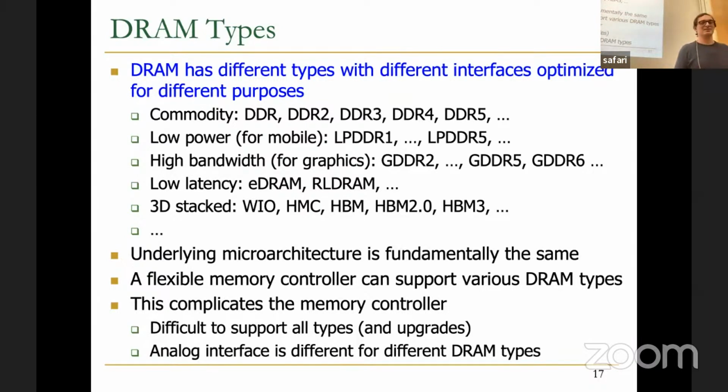Hopefully it works. But now, let's say you design for LPDDR6 or LPDDR5, right? That happens in a lot of SoCs today, for example. But if you want to add, for example, HBM on top of that to the same chip, now you have to completely redesign the analog and mixed signal interface. So it adds to your cost. Probably more than doubles your cost because you also need to figure out where to lay these out on your chip, because your chip is in the end limited by the I/O pins, right? So this is really the difficulty of adding more memory types to the same chip.